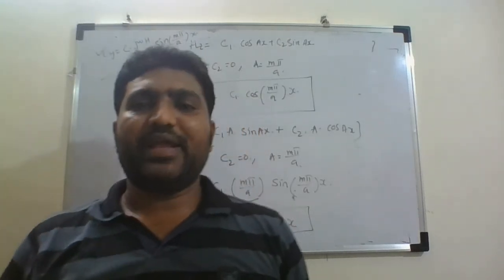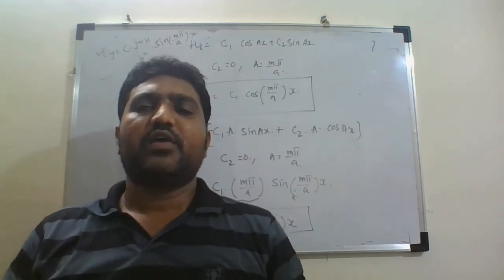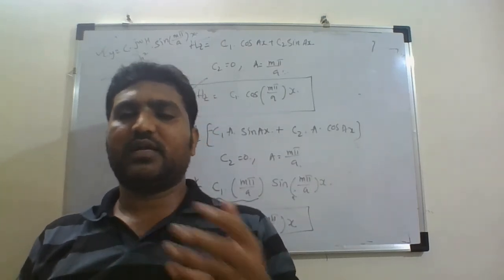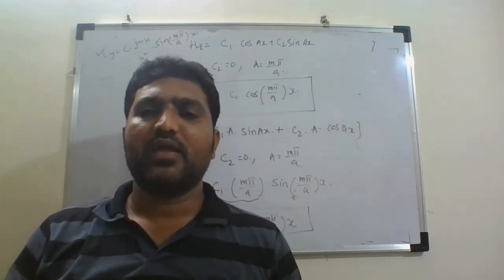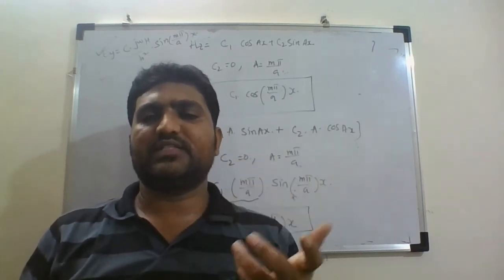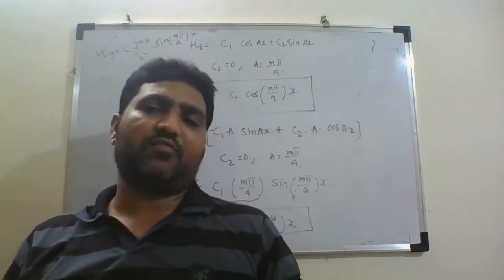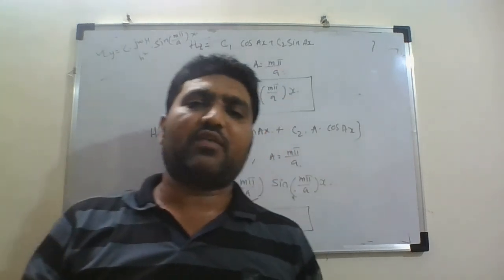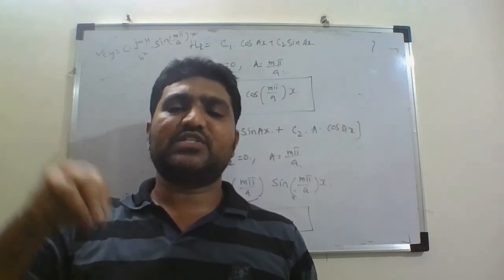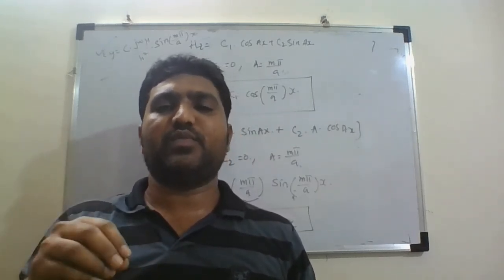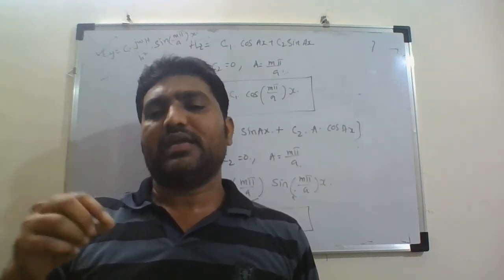So in summary, a brief summary. As we discussed, in planar waveguides we can have three modes: TE, TM, and TEM. Now we are discussing the wave propagation for a TE wave, a transverse electric wave. We get a transverse electric wave whenever I incident a vertically polarized wave, that means Ez is equal to 0.